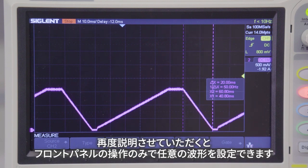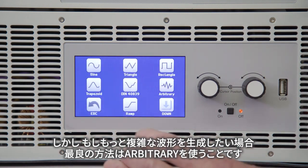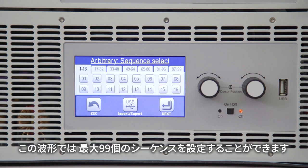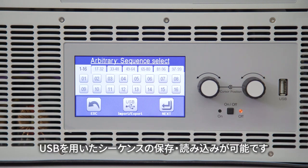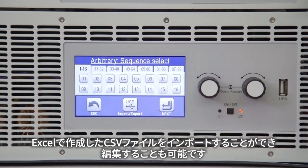Now, one of the things you can do is program all this from the front panel. You can see it's a very nice touch screen. But if you want to create a very elaborate profile, some of the best things to do is create an arbitrary current wave shape. This allows you to program a sequence of between 1 and 99 sequences. You can import or export through a USB. You can take your files, create them in Excel, save them as a CSV, and download them directly into the DC load, and it will recreate that load profile that you've done externally.